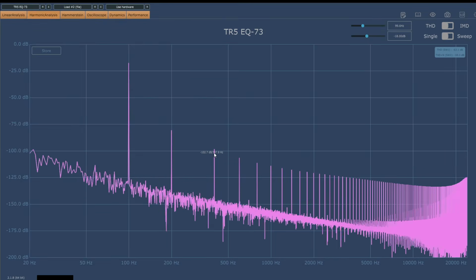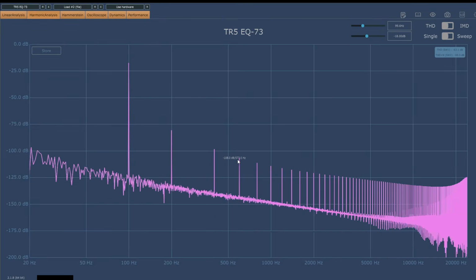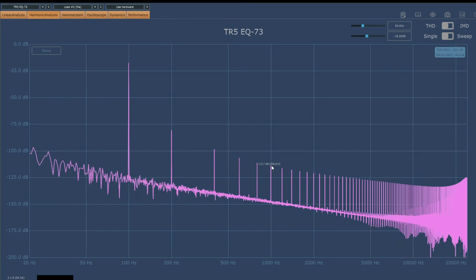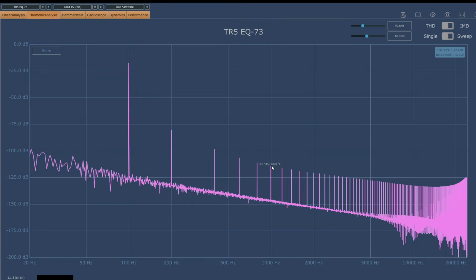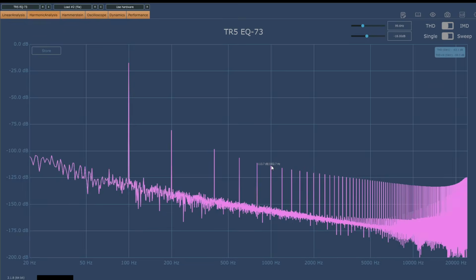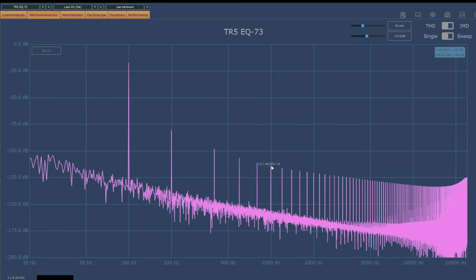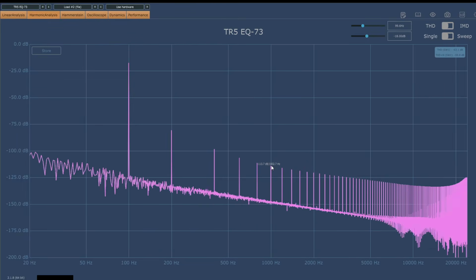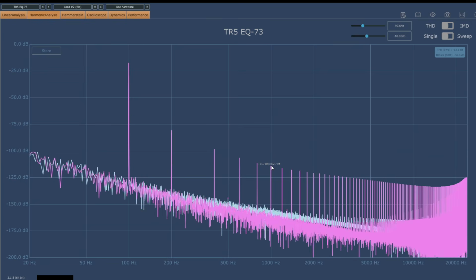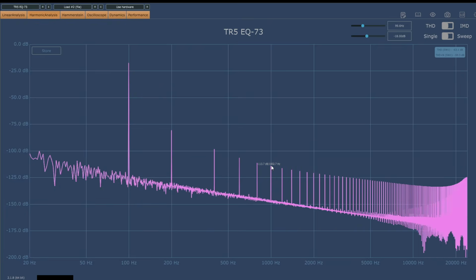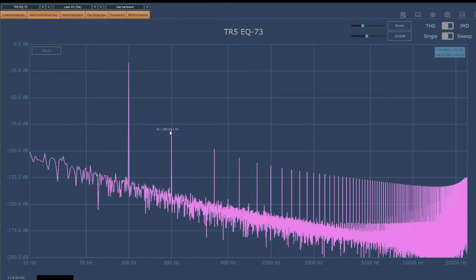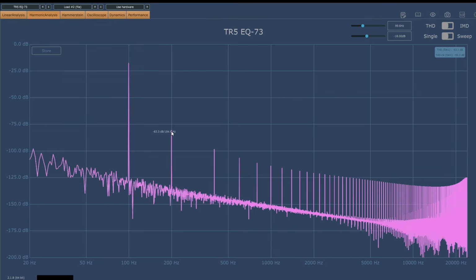Next up is 400 Hz, the fourth harmonic. Then 600, 800, 1K, 6th, 8th and 10th harmonics respectively. Notice that the odd harmonics are missing. Even harmonics tend to sound sweeter than odd harmonics, suggesting this preamp model will add a subtle sweetening effect to the signal. But once again, let's pay attention to the vertical scale. With default unity gain settings, the second harmonic is about 60 dB lower in level than the original signal, so we can expect that sweetening to be quite subtle.